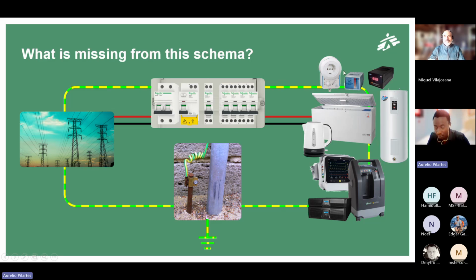And then on the other side, we have these devices here that were mentioned. So we have the AVRs to protect all the devices against voltage fluctuation. We have the voltage limiters, and we have the UPSs. So as you mentioned earlier, these ones are here to protect the equipment, while these ones are here to protect the installation, the electrical system itself.